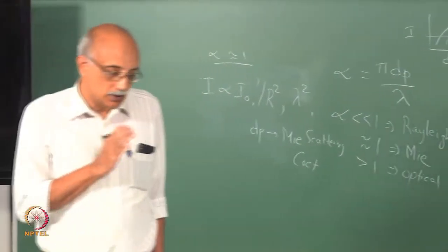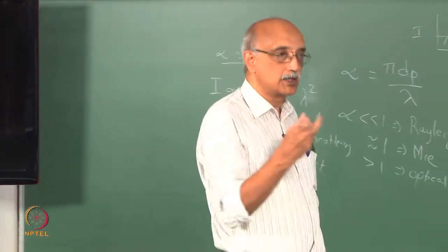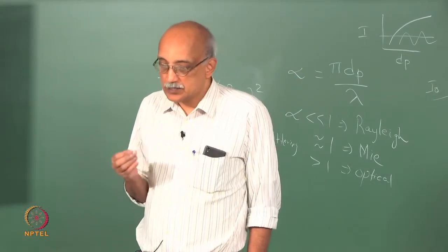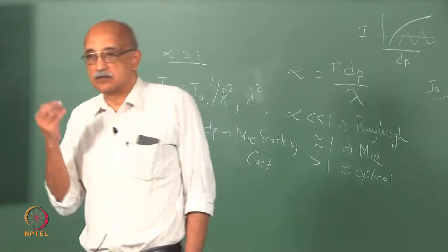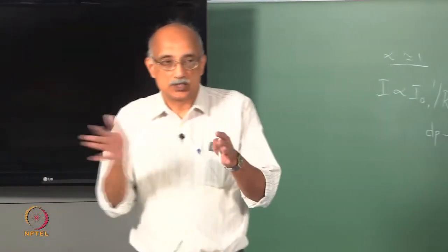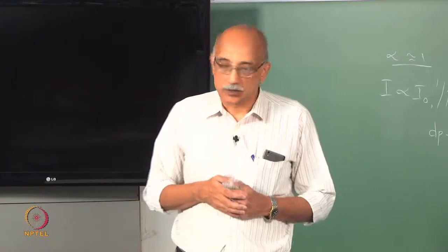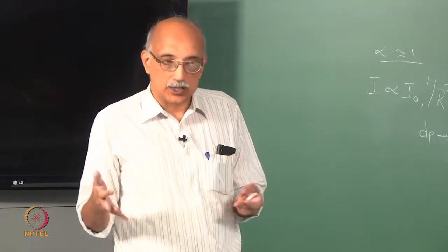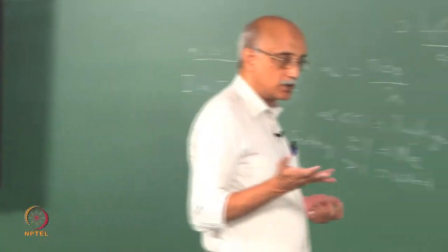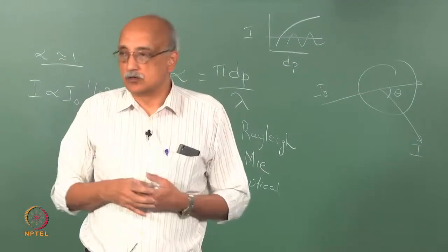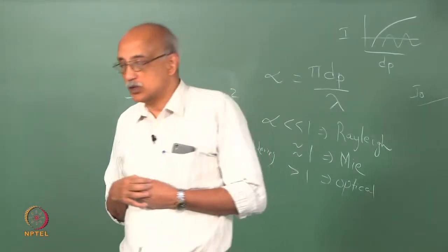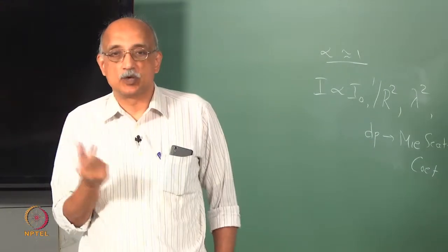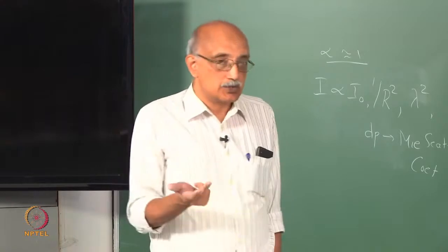Okay. So resolution has a lot of influence on how concentrated a sample can be, and you would still be able to measure it. An instrument that has poor resolution can only handle very dilute samples where there is a large distance of separation between adjacent particles. And finally, U stands for uniformity. Any sample that you measure, it is a sampling technique, right. So you are not really measuring the entire volume of material. So whether it is an airborne particle counter or a liquid particle counter, you are typically only measuring less than 1% of the volume that is available, and you are drawing conclusions based on that.